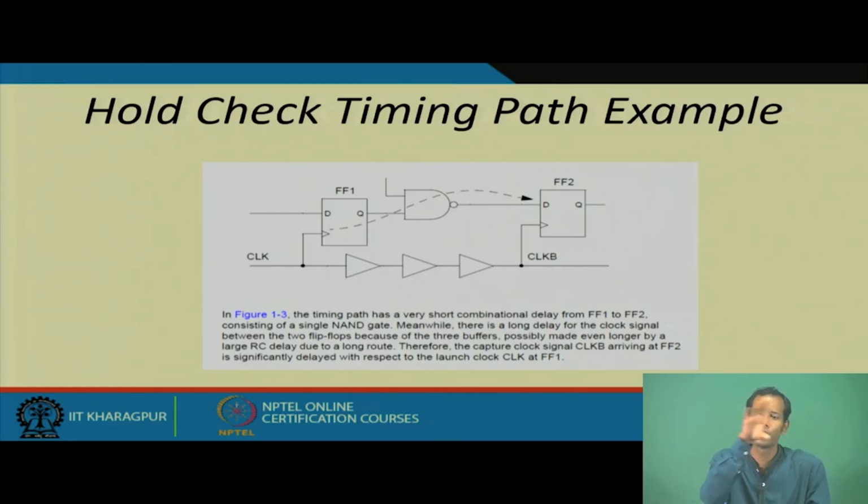They are distributed all over, across all the corners of the core. Your clock source comes in through one particular location, and from that location you have to distribute the same clock to every sequential element present in your circuit or core.